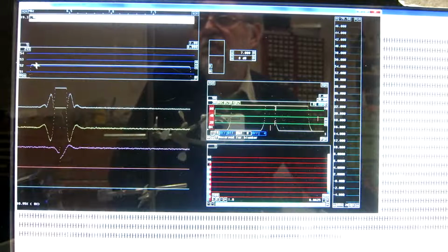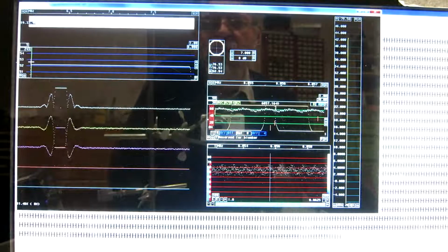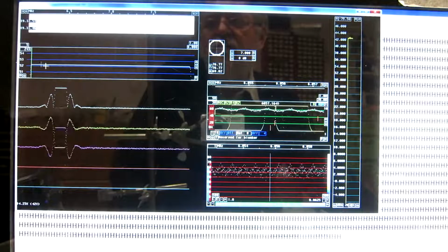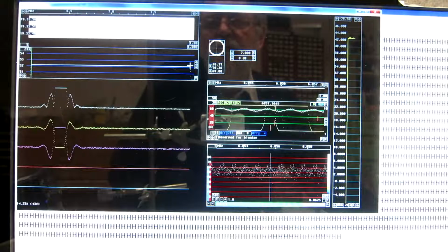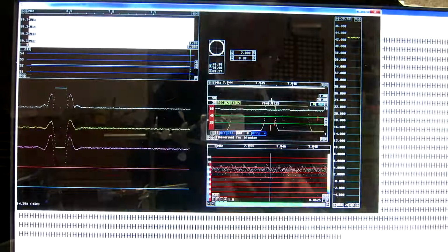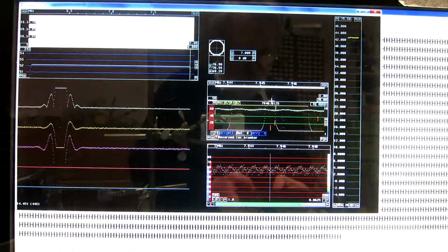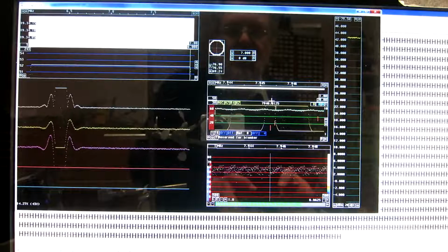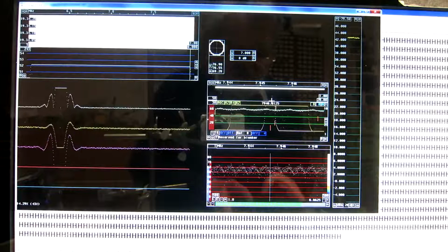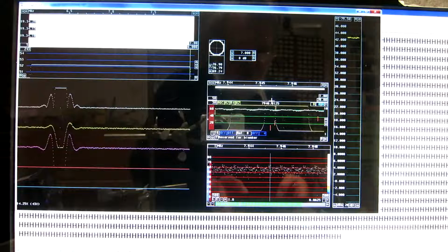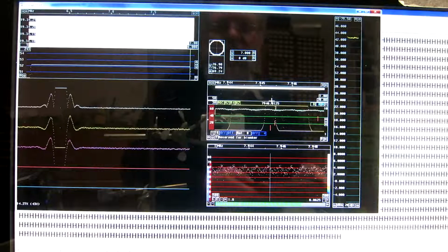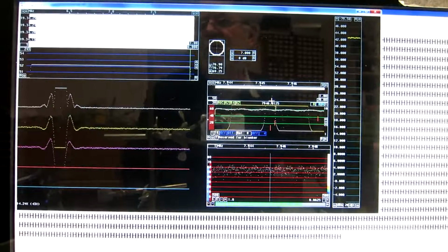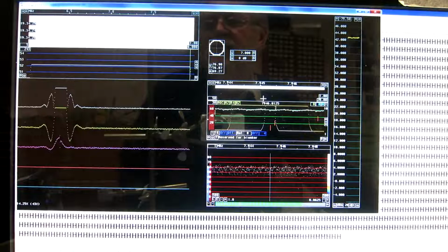And you see we have from here, that's 6.056 to here 6.066 minus 7.946 equals 1.88 megahertz. Perfectly flat passband to within better than 1/10 of a dB.